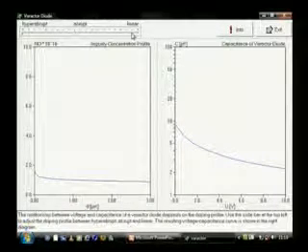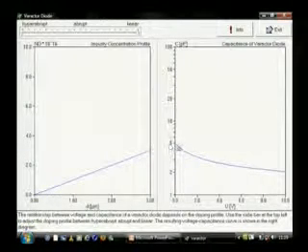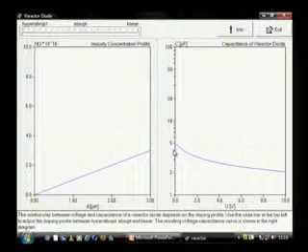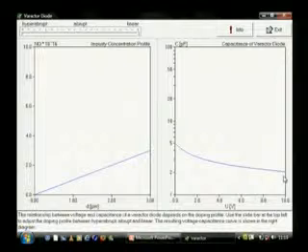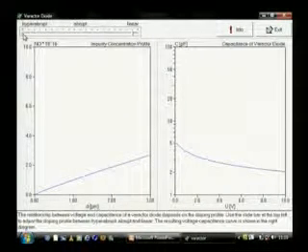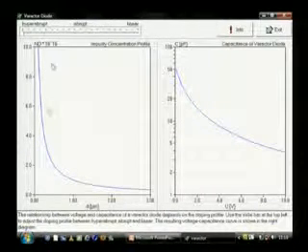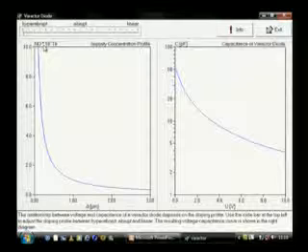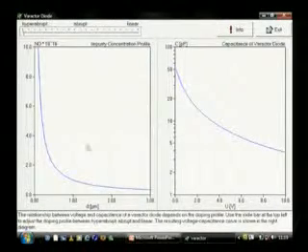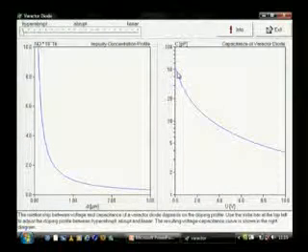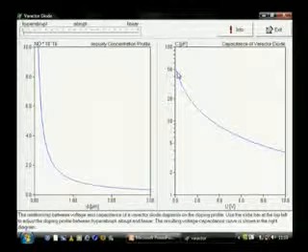If I change the doping profile to linear, the initial capacitance is higher, and this capacitance decreases as it goes to higher voltage. The inverse situation occurs in the hyper-abrupt doping profile. In the hyper-abrupt doping profile, we have a very high value of doping, and due to this very high impurity concentration we can have a much larger amount of capacitance.